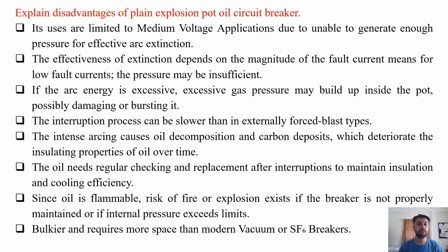Its uses are limited to medium voltage applications due to the inability to generate enough pressure for effective arc extinction. The effectiveness of extinction depends on the magnitude of the fault current, which means for low fault currents the pressure may be insufficient.